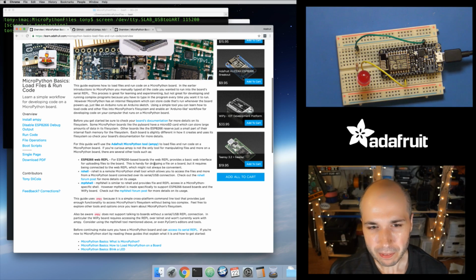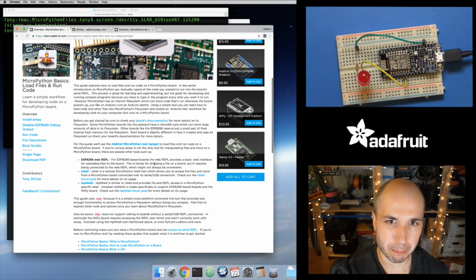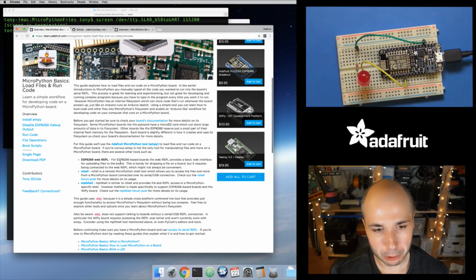So that's really cool. And we'll see that there are some powerful things you can do when you put files onto a board. Like, there are certain special files that when you put code inside of them, they'll be run whenever the board boots up. So that's maybe how we can solve the part of the problem of how you have code run when the board starts up. And then the other part is, how do we actually edit these files? Because the board has a file system, there are some tools that people have created that let you copy files from your computer onto a MicroPython board. That's pretty powerful, because with that, I could go into a text editor on my computer, write some Python code, save it locally on my computer, and then run a little command to copy that file onto the MicroPython board. And I talk about here, there are actually multiple tools that let you do this.